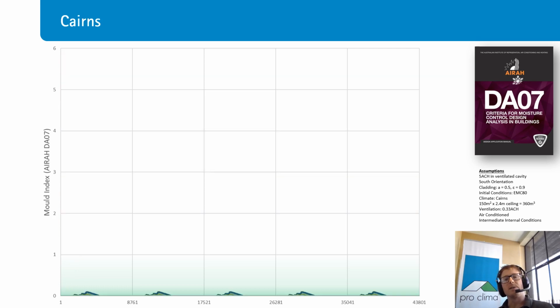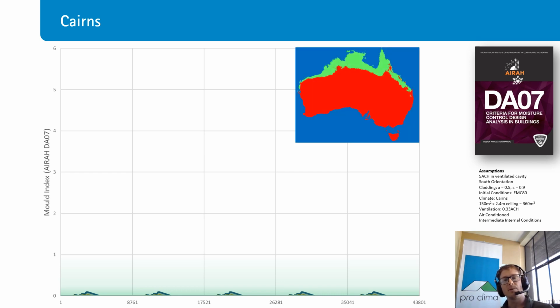If I take that system to Cairns and I build rigid WRB systems with peel and stick membranes over the top in the tropics, then I'm highly likely to get zero or very little indicators of mold growth behind that WRB system. And that's because the water vapor is driving the other way, from outside the building to the cool inside of the building. In that case, external air tightness using a rigid WRB system with a membrane over the top works. So up in the tropics, it's highly likely we can use this exterior air tightness layer to achieve passive house outcomes.